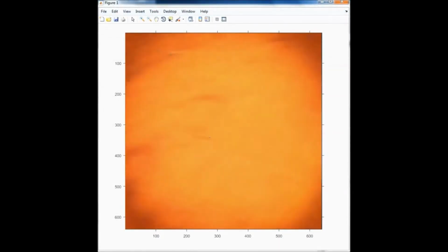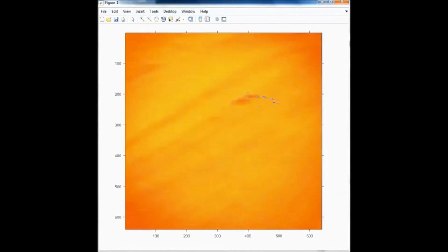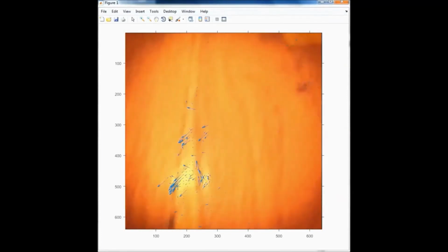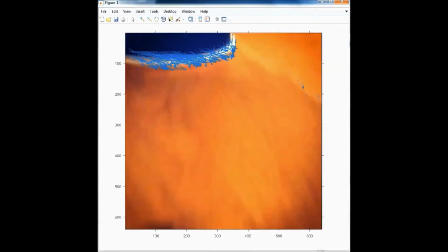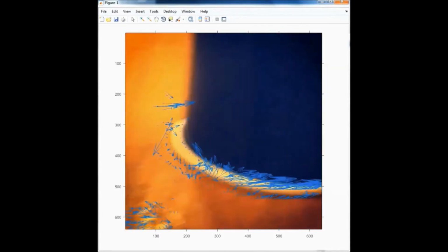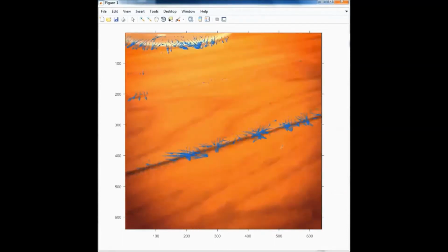Optical flow computation involves estimation of image motion fields from temporal variations of spatial image data. Optical flow fields correspond to 2-dimensional projections of 3-dimensional movements of surfaces in a scene, either due to dynamic objects in the scene being imaged, or due to ego motion of the robotic platform on which the camera is placed. Optical flow estimation is used to characterize and quantify the motion of objects in a video stream, often for motion-based object detection and tracking systems.